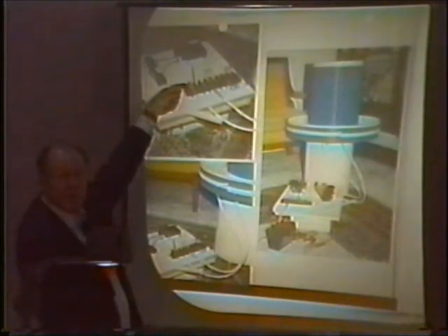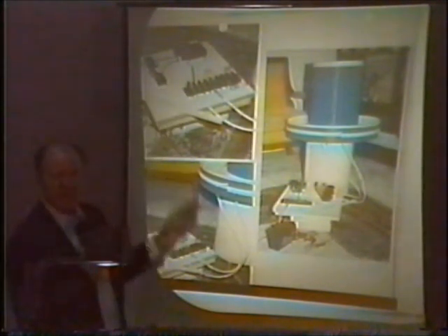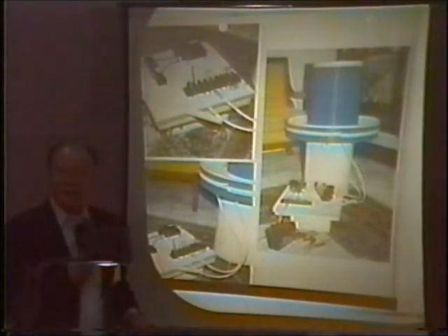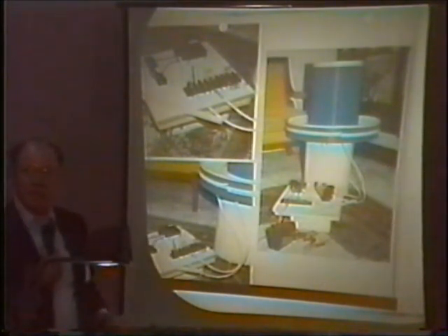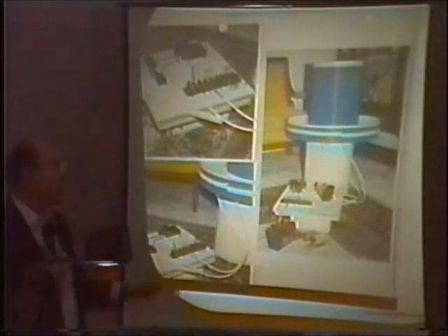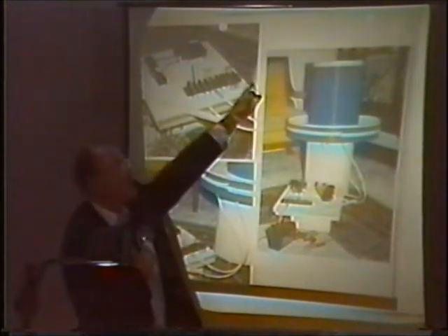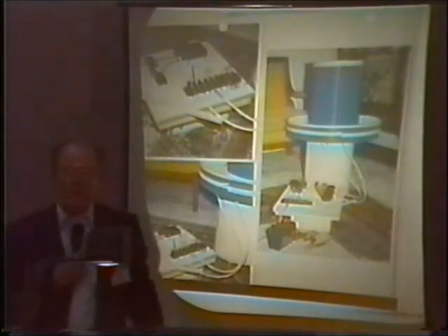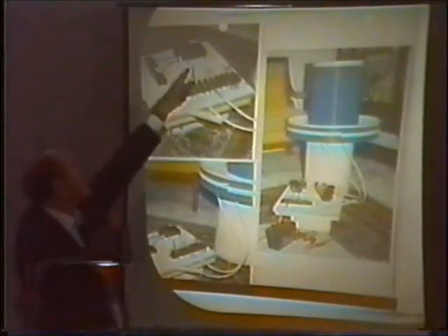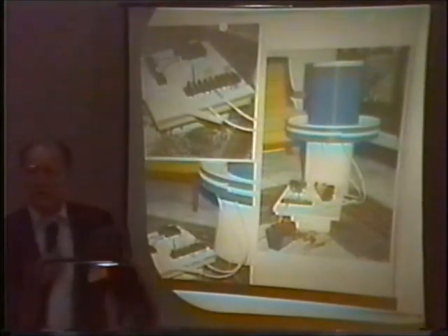Okay, somehow you have to get back to your negative pole on your battery or a ground plane or something like that. So in this case, there's another cord that hooks onto this, and it goes to an earth grounding that comes off of one corner of that high voltage coil. It's a small orange and yellow mechanism in a U-shape right behind the spark plug.